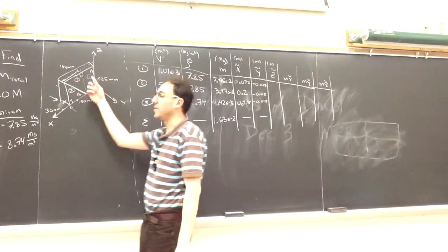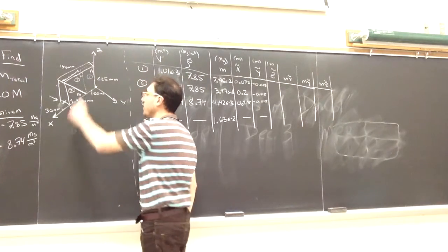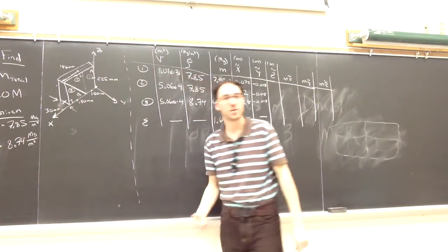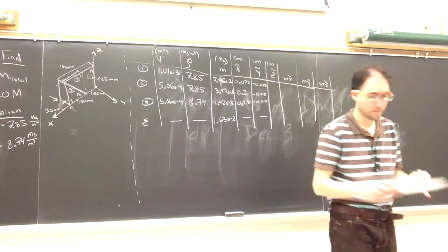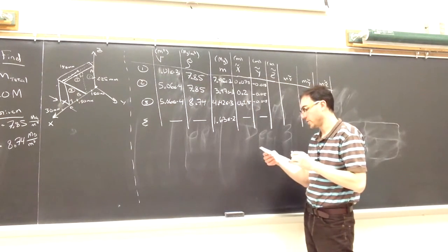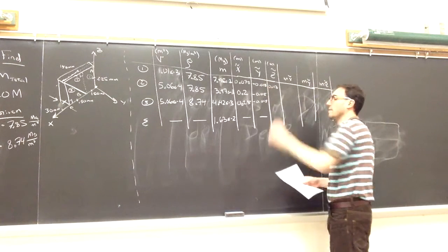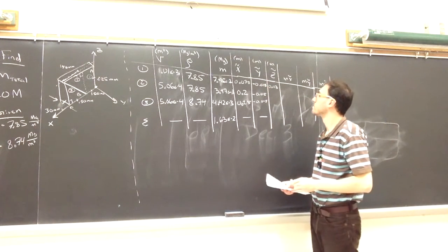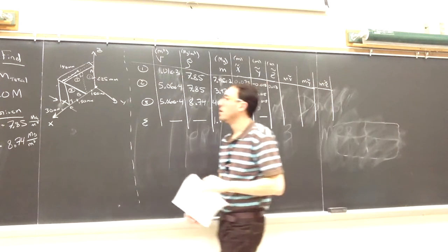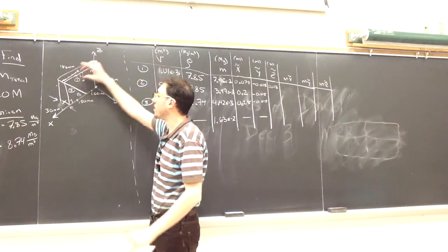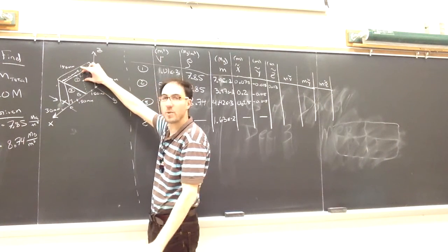And now the z tilde, because we're in 3 dimensions. For shape number 1, I have to go to half of its height from the origin. So 225 divided by 2. So in the z direction, for shape number 1, I get 0.113. For shape 2, 1/3 of its height away from its right angle, so that is going to be 1/3 of 225.